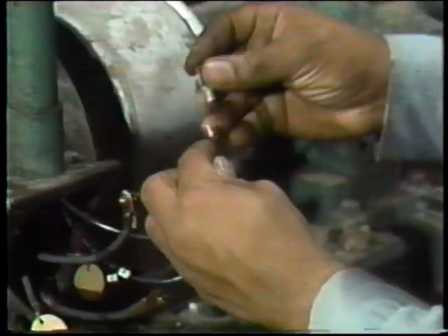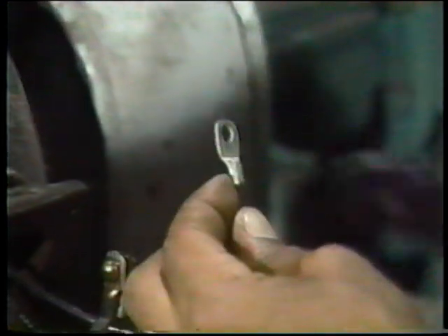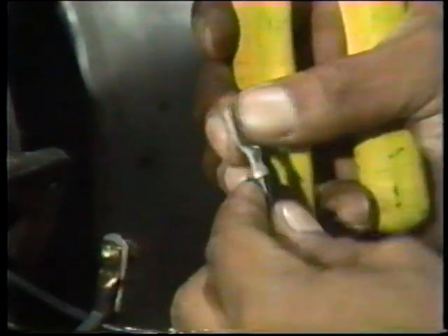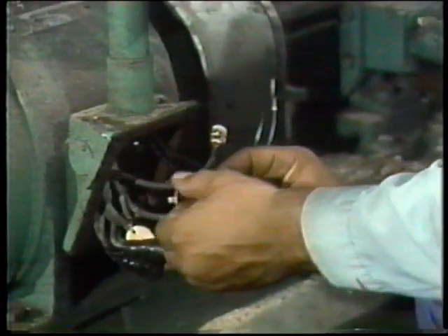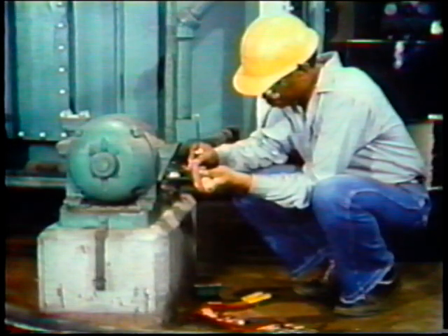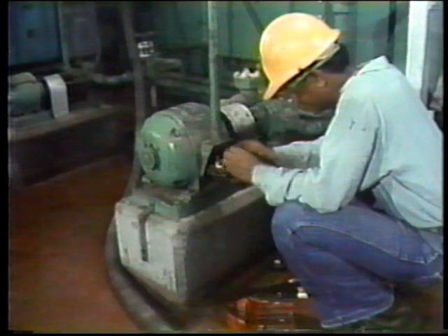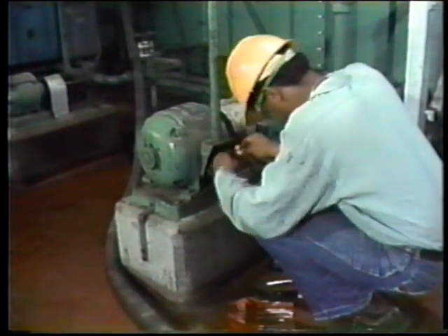He puts the lug on the end of the conductor and, using the crimping tool, crimps it, making sure the crimp is well centered on the lug. It's a good idea to give a test tug on the lug to make sure it's securely fastened to the conductor. Next, using the nut, bolt, and lock washers that are on the motor lead, he'll attach the lug to the lead and secure it with a spin-tight and a screwdriver. Once that's tight, Bill will complete the last mechanical connection the same way he did the first two.